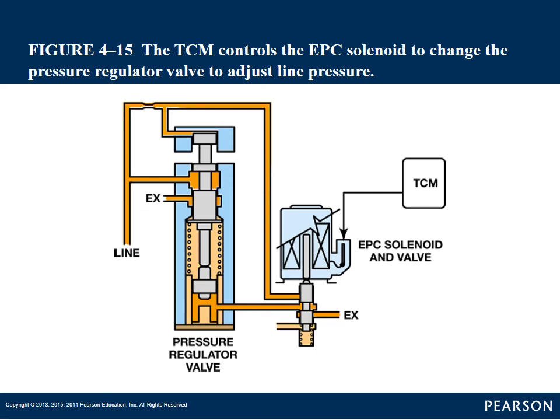So if they want more mainline pressure, they apply more pressure to the backside of that valve. This is an applied type. On some, there's pressure on the back of that valve, and then they'll use a solenoid to exhaust pressure in order to control how much pressure it takes to push that valve, and whether it increases or decreases mainline pressure.